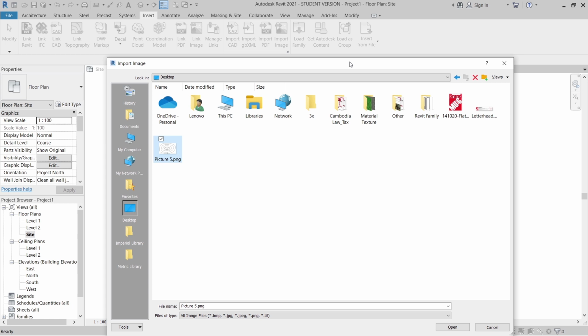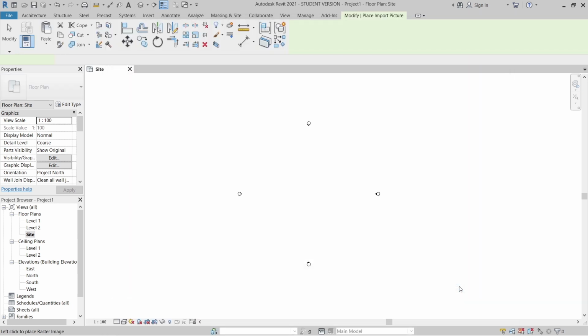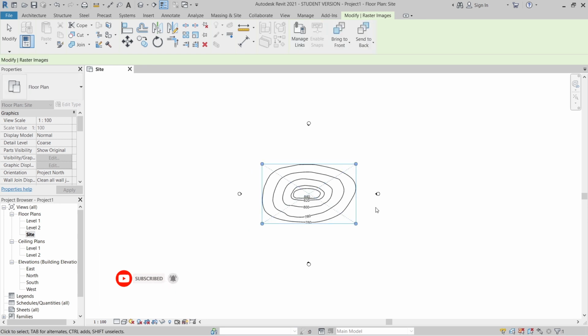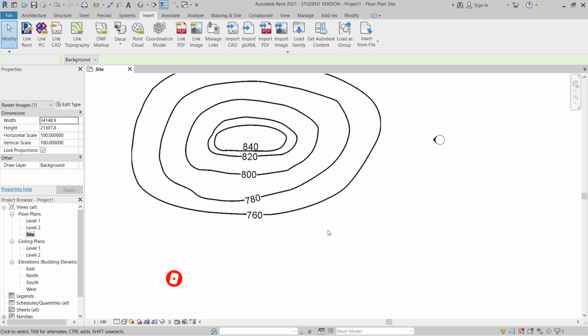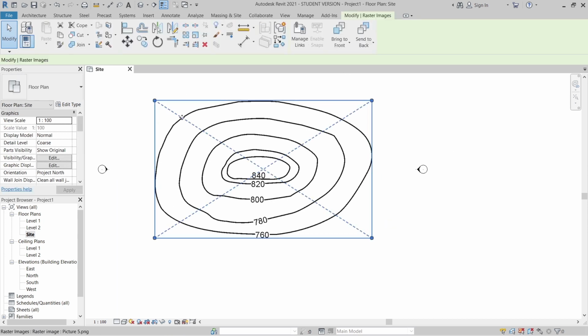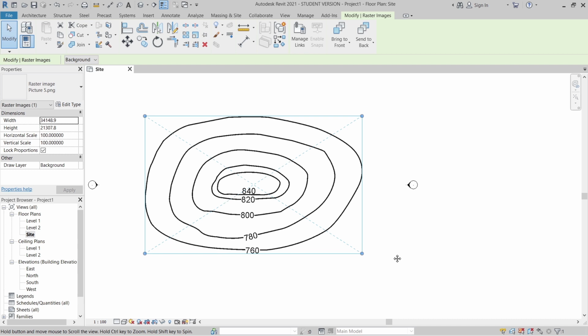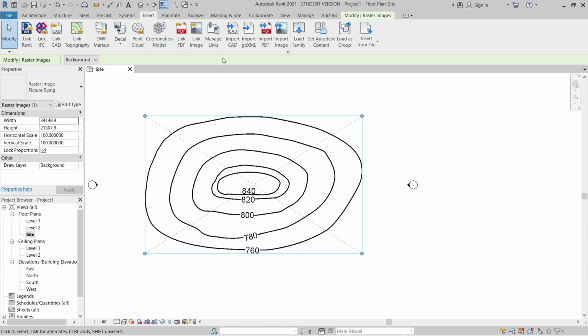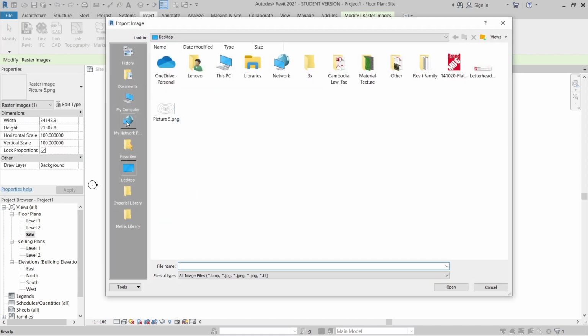So now I'm going to open it up. Once I open that, I can place it anywhere that I want. I just simply place it in the center here. Then I'm going to zoom in a bit. Basically, for the topo surface point here, as I remember, it's 15 meters. Let me insert another one first. I'm going to import, make sure everything is correct.